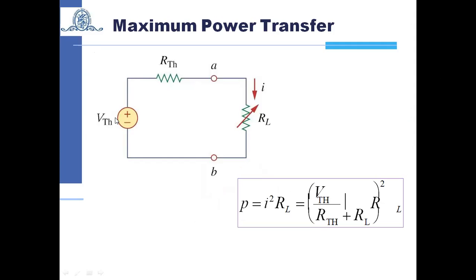Thevenin equivalent means here we have a Thevenin voltage, and the Thevenin resistance RTH is in series with the Thevenin voltage. If a load is given, you can take that load at the output directly. If no load is given, you can take VOC and RTH, because that voltage will be the open circuit voltage.